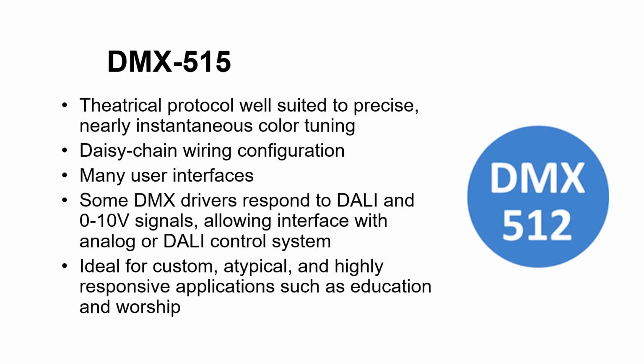Originally designed for theatrical applications, DMX has the digital capabilities needed to address and send multiple signals to an individual luminaire to control color and intensity of multiple LEDs. There is an almost instantaneous response by the luminaires to the control signal. DMX is capable of two-way communication if this feature is desired and enabled. Daisy-chained wiring is required, which means each device must be wired to the next in succession. A broad range of user interfaces is available, with color precision and repeatability being somewhat dependent on the interface chosen.